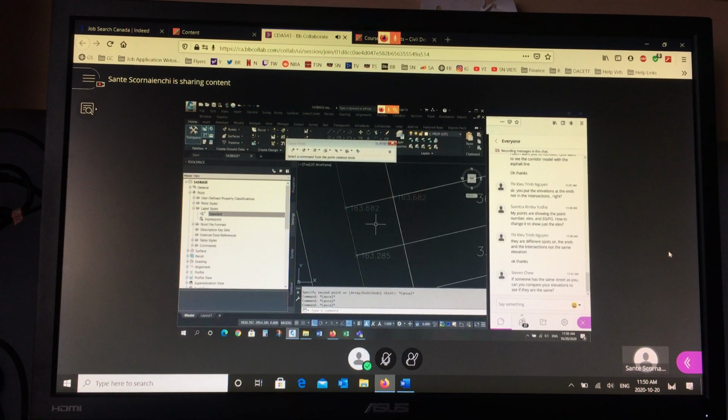If I copy this point from the node, and I put it on this endpoint, watch what happens. It becomes 0. Okay? So I don't want to do that. Don't take it from the node to the endpoint. Take it from the endpoint to the endpoint.